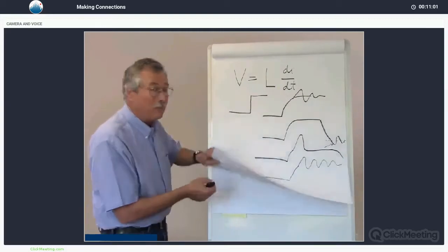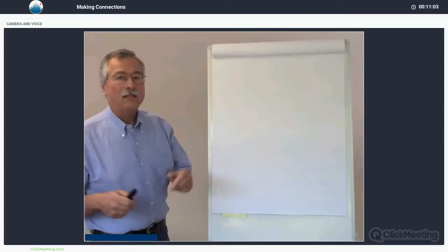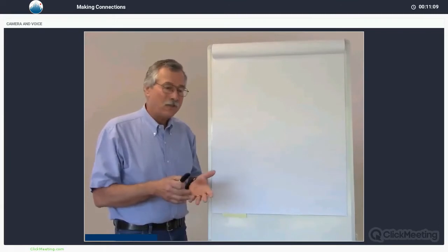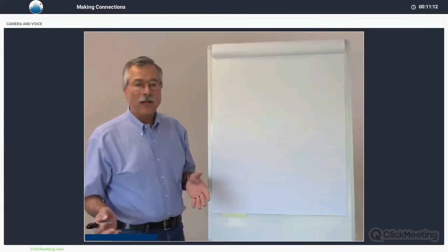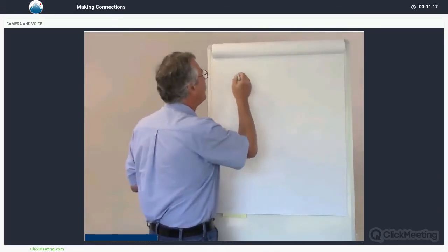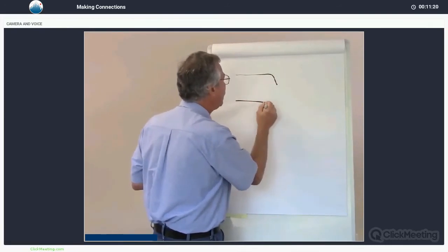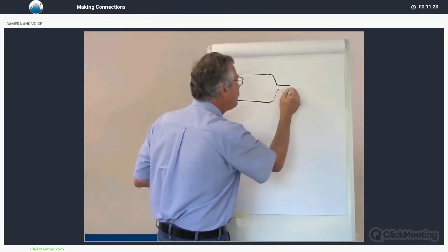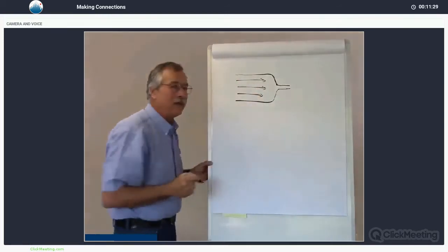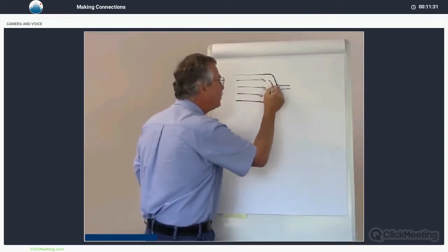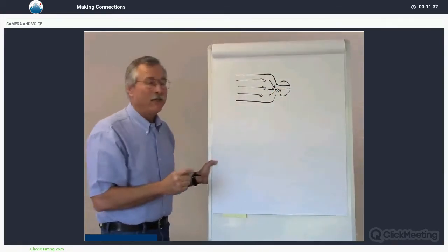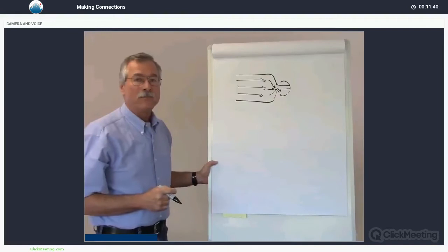Where does inductance come from? Any conductors in our system: the traces on the PC boards, the leads of the components, the cabling between the laser diode driver and the laser diode package itself. What can make this worse is, let's assume we have a wide trace or a wide cable, and then we neck it down. That current that's flowing evenly through this nice wide conductor suddenly has to fit into this narrow space, and this is an area of high magnetic field. In other words, we have just created an inductor.